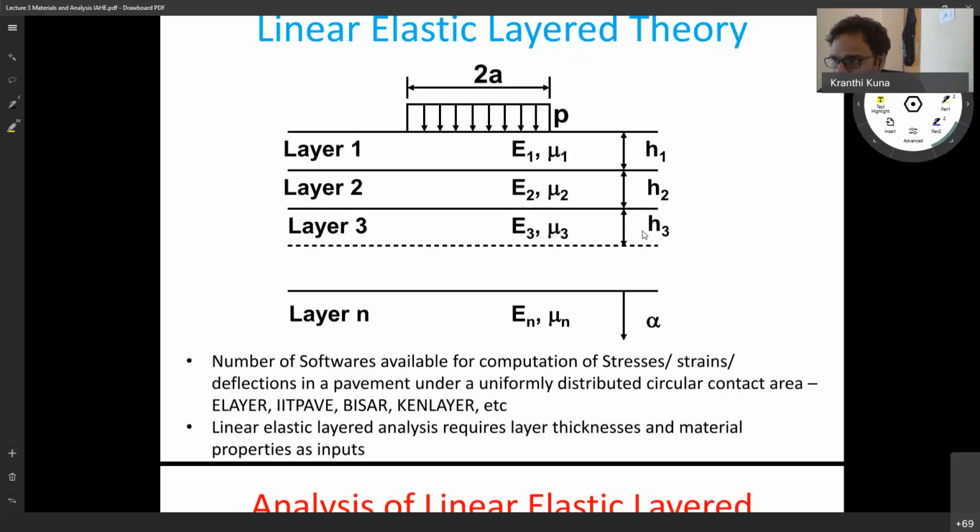You are talking about granular materials. Are you talking about CBR value or grading envelope? For the grading envelope, we are giving an upper bound and a lower bound. So it is not explicit, but there is some factor of safety inbuilt. But for unbound material, in what way are you talking about factor of safety?